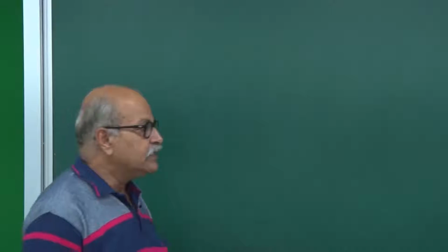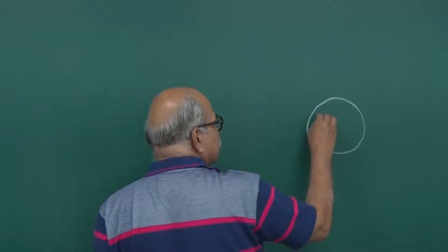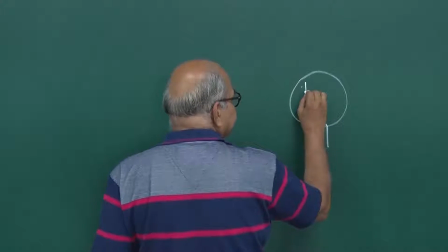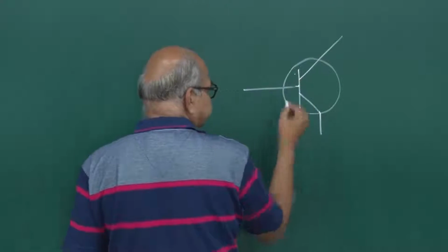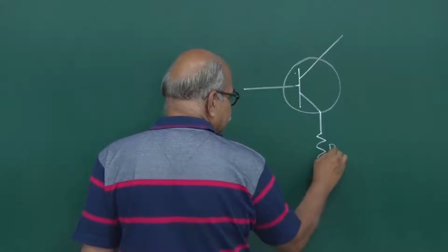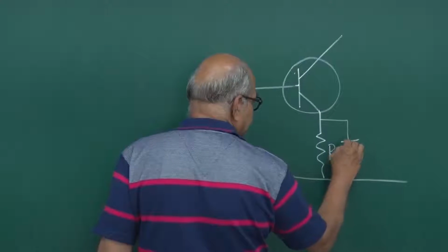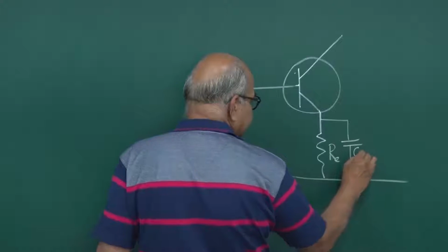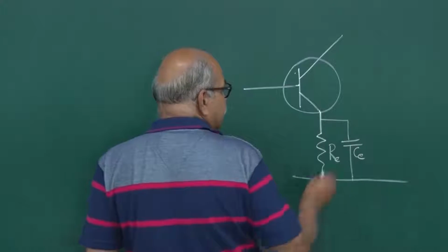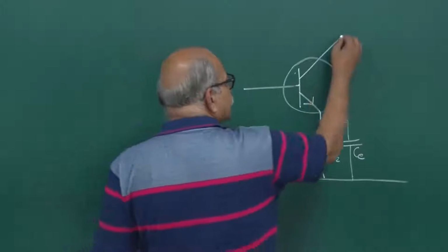So, in a transistor amplifier in common emitter configuration, you have this emitter here and collector here, base here. Then you put this to ground through some resistance. In the actual case you also put some capacitor, so that the alternating signal is bypassed from here. And then this side should be forward biased, and this is an NPN transistor, so this should be forward biased.